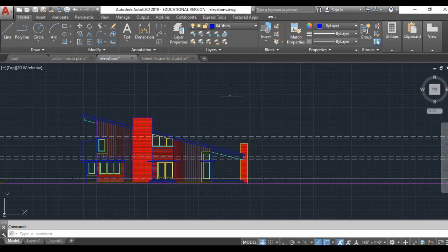I see the whole building, right? What you're actually taking away is the ground or the earth in front of the building. You have to stand in front of the building essentially to see it, and so that's your cut line, is through the ground. Any cut line is going to be the thickest line weight. And so we can see in this drawing here, I have it as magenta.